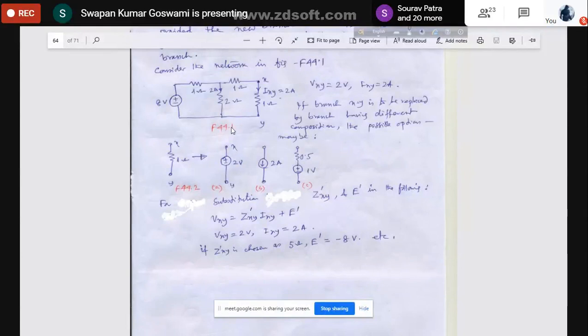Whatever the parameter, if it is an inductor, that will be constant. If it is a capacitor, that also will have constant capacitance. So this is the assumption. In fact, what happens in circuits is that most of the elements are not linear in that sense. Say, resistance changes with temperature, resistance changes with current flow. But for all the circuits we have considered, the physical resistances are such that even though there are variations, those variations are so small that you can neglect them.